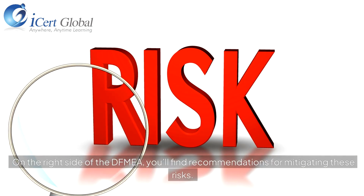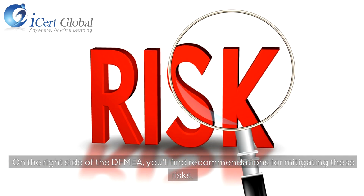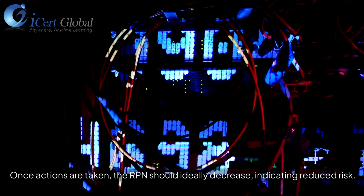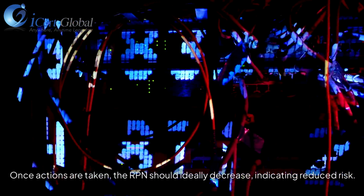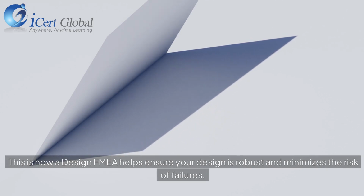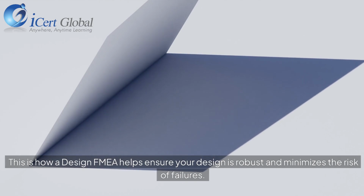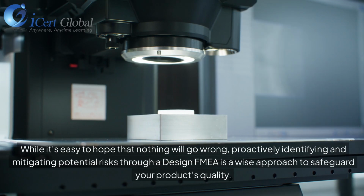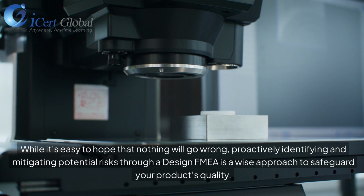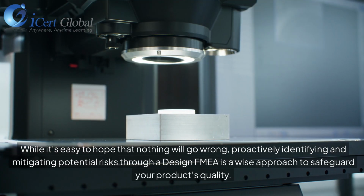On the right side of the DFMEA, you'll find recommendations for mitigating these risks. Once actions are taken, the RPN should ideally decrease, indicating reduced risk. This is how a design FMEA helps ensure your design is robust and minimizes the risk of failures. While it's easy to hope that nothing will go wrong, proactively identifying and mitigating potential risks through a design FMEA is a wise approach to safeguard your product's quality.